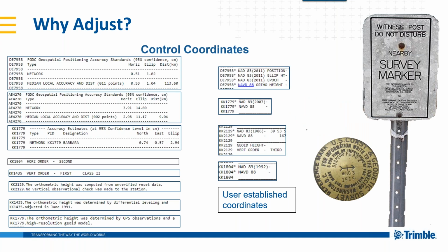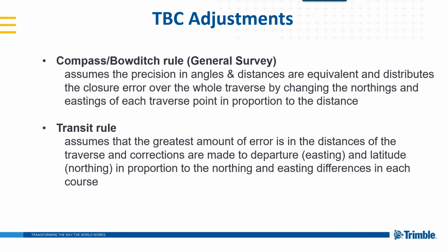On top of that, these days we have different coordinate systems that are published through our NGS data sheets or other sources, with different qualities, and so we have to pay attention to what these numbers are, these coordinates we're using. Where do they come from? Should we use a NAD 83 86 coordinate with a 2011 or 2007 coordinate? How do we handle that? What do we do with it? So we have to pay attention. Not all these questions are going to be answered in this topic, but coordinate control is a whole other issue. We won't get into that.